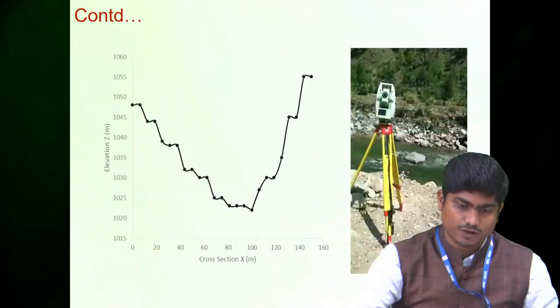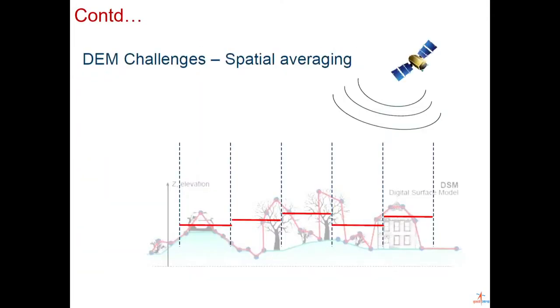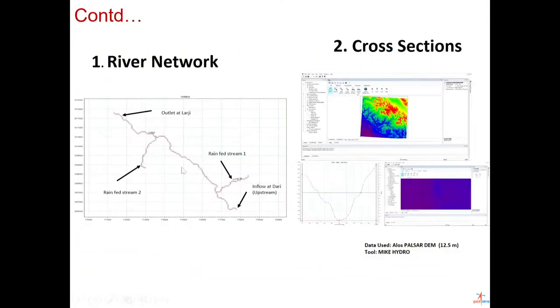Now again, if I go back to my river network, here you can see that I have four boundaries, right? This is my upstream boundary, this is my downstream boundary, and these are the two tributaries. Again, these are open ends, so those also are boundaries. I have to give certain information so that the equation will be closed and accordingly we can give a solution to that equation. So at each end you have to give the boundary condition.